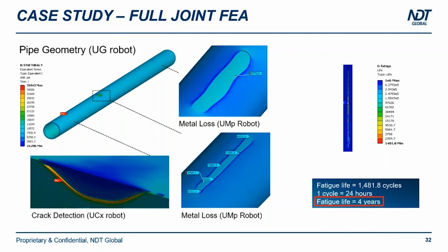After the runs, after the data analysis was finished, and as a result of the fitness for purpose analysis, some anomalies were found as not accepted to remain in service. It's important to comment that this assessment was performed using level 1 and level 2 methodologies, common and traditional methodologies. The problem was that these anomalies were located in the same joint, in the middle of one high consequence area. The presence of one water body and two nearby villages generated a very complex scenario to repair immediately.